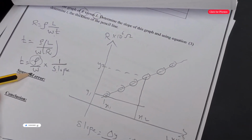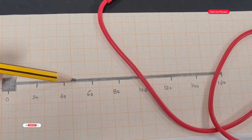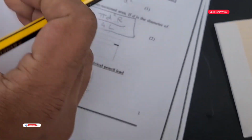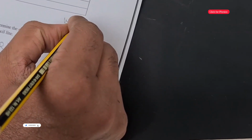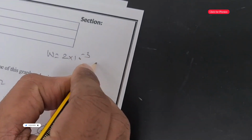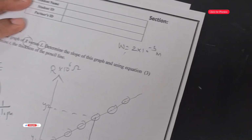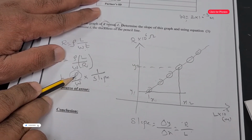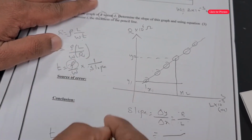Clear? And also, what is the width? If you just see the line, the width of this line is exactly 2 millimeter. So the width is 2 millimeter, and when I convert millimeter to meter, I have to multiply by 10 to the power of minus 3. So take the value, substitute here, take the resistivity value from the first table, and take the slope value, substitute here, and you will get the thickness.